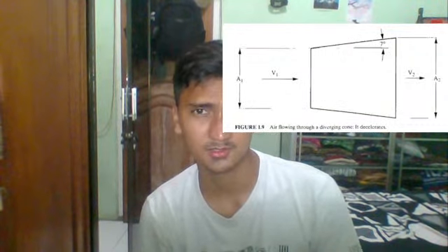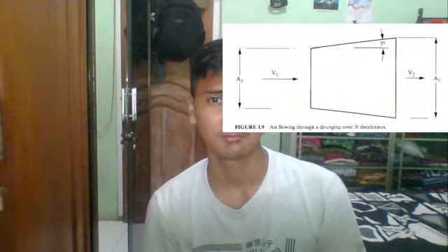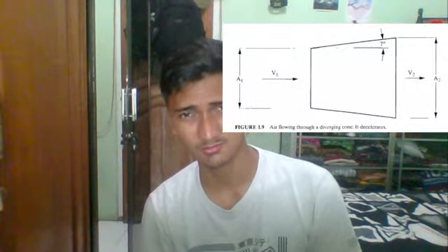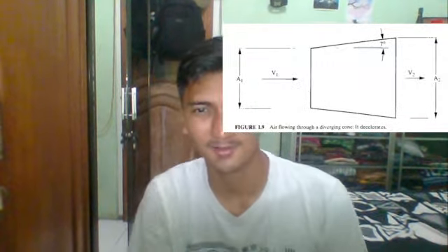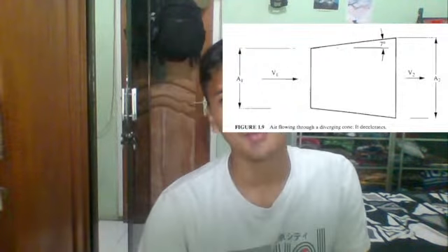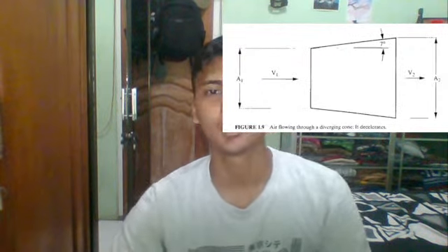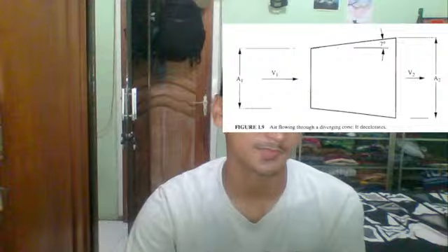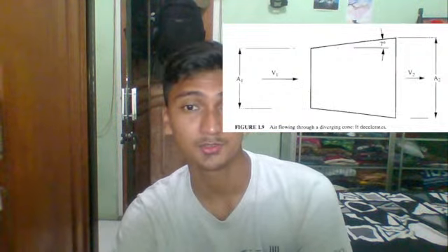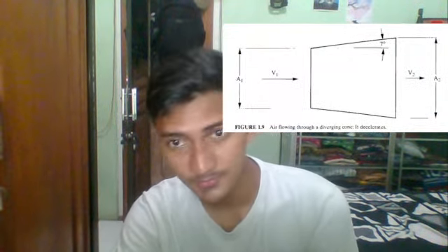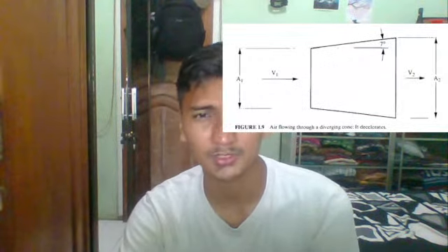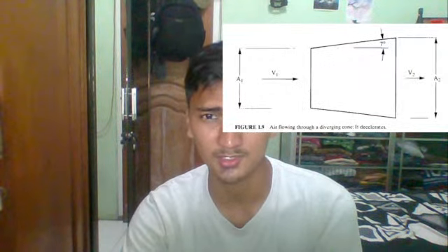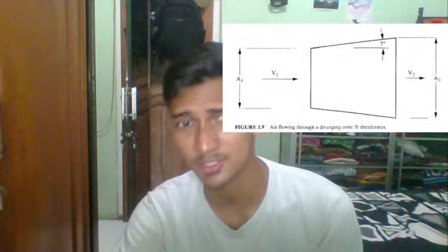And the question is, will this difference in kinetic energy be lost? Will it be or not? Yeah, about half of it will be lost, right? The answer is mainly due to turbulence. The other half, believe it or not, will be regained by an increased static pressure as stated by Bernoulli theorem,